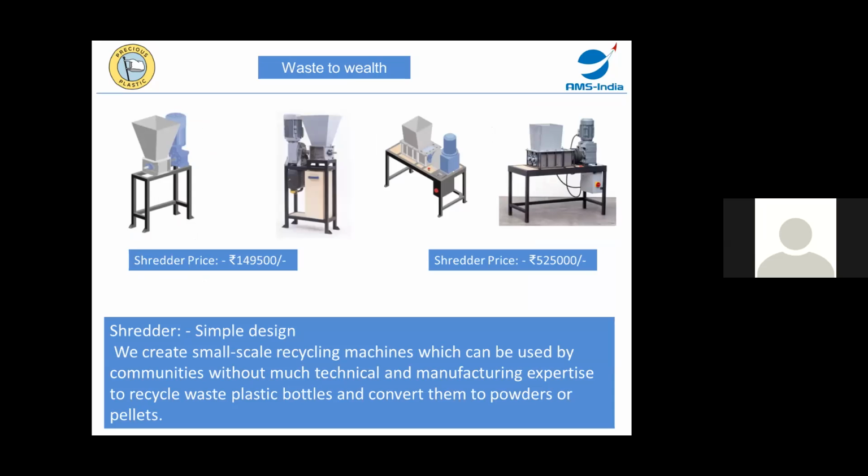While shredding, we don't have to segregate the plastic. Once we shred it, we can just put it into a bucket consisting of this liquid, and whatever floats in this can be segregated. Then this shredded plastic powder can be taken, and there are a lot of companies who will buy plastic powders which are segregated and given to them in different colors also.